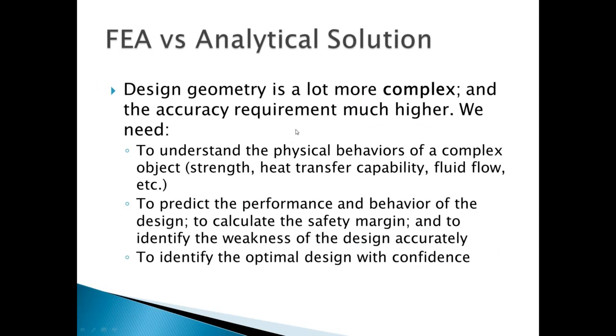So yeah, as I was saying, we need to understand more complex parameters such as strength, heat transfer capability, fluid flow, which is especially useful for seepage, etc. And we use it to predict the performance and behavior of the design, to calculate the safety margin, and to identify weaknesses of the design accurately. So ultimately, with finite element analysis, although it requires more effort to conduct, you do get more accurate results. You can get more optimized designs that will ultimately cut costs.